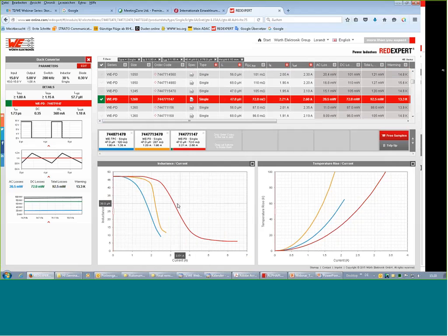If you go to this graph and you see this inductance, you will see that many inductance steps are measured values. So it's not just a simplified Steinmetz formula, which is not so valid when you're not running on a duty cycle of 50%. In this case, we are running on a duty cycle, let me check, which I chose as 35%. So the duty cycle error based on the Steinmetz formula will not be so good in this case.